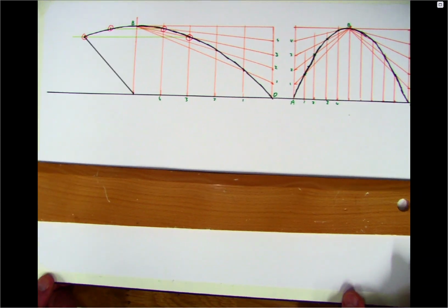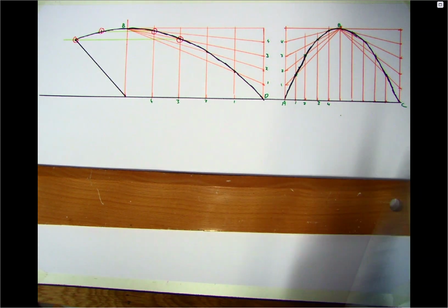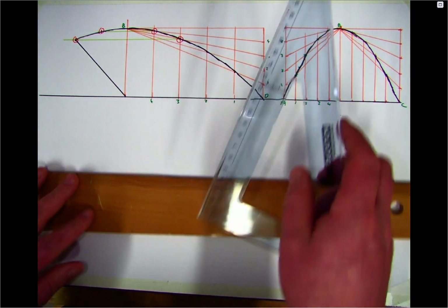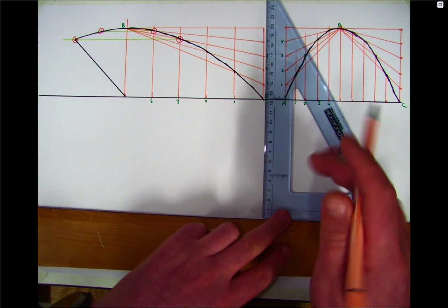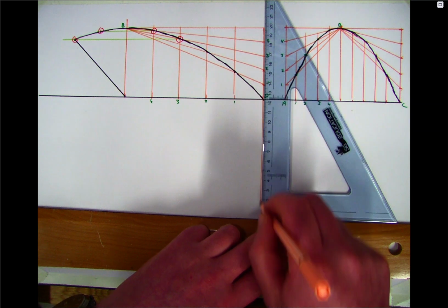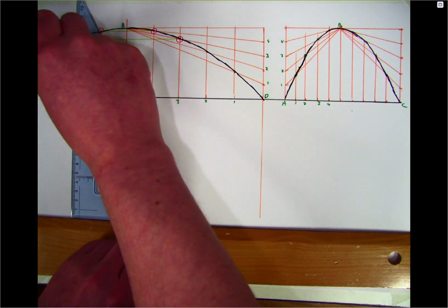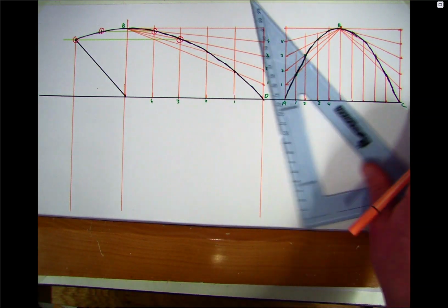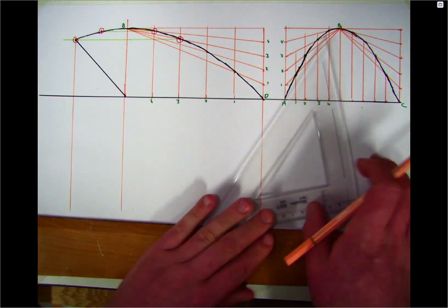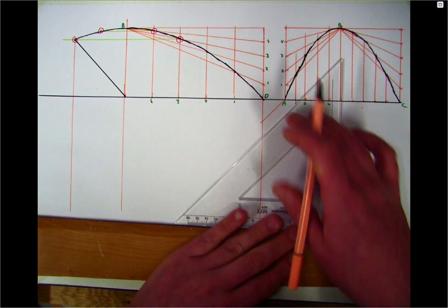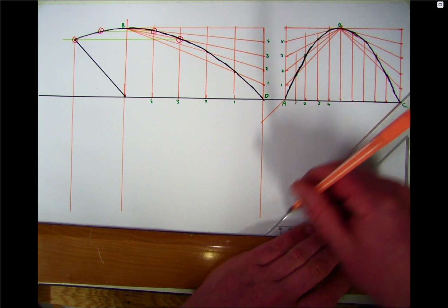So I have part A and part B done there, the elevation and then the end view. So the next part it says is to draw the plan. So what I'm going to do first is literally create out the space that I'm going to need for this plan. Okay, so I need my 45 to be set up then to project down this way.